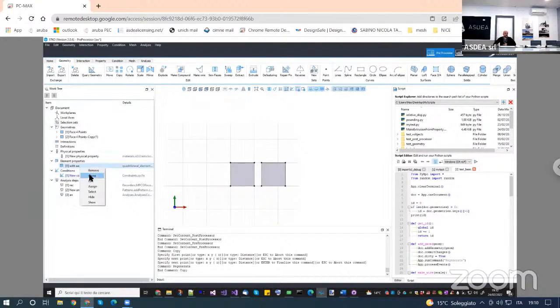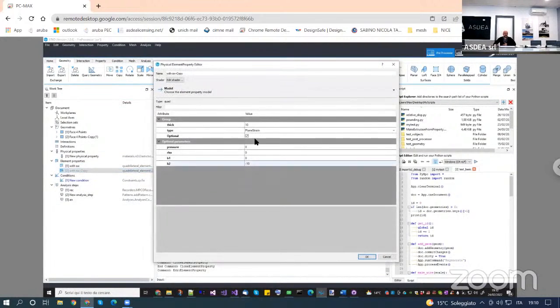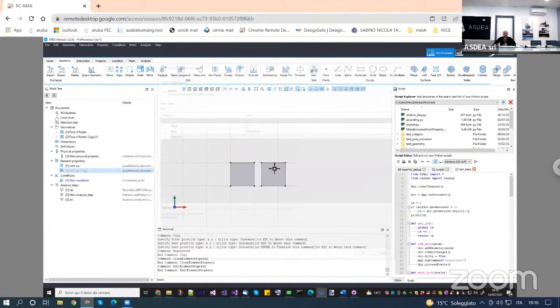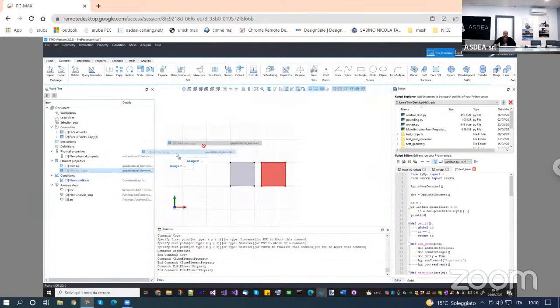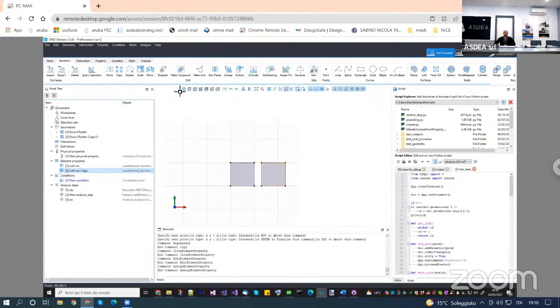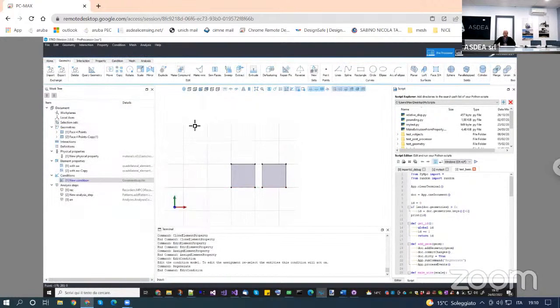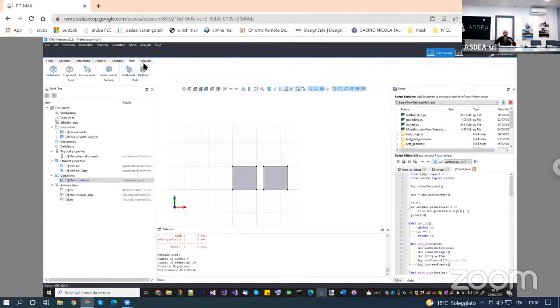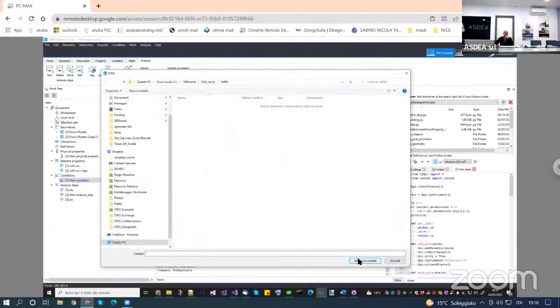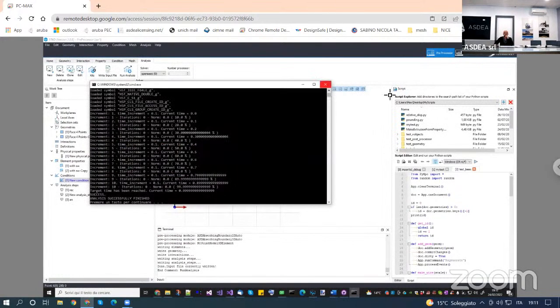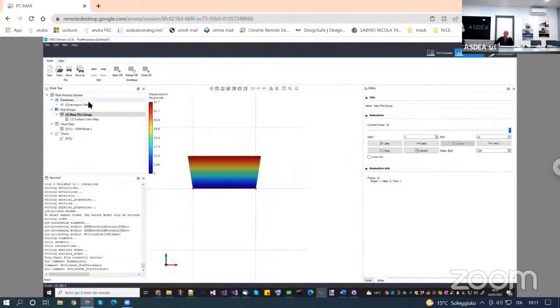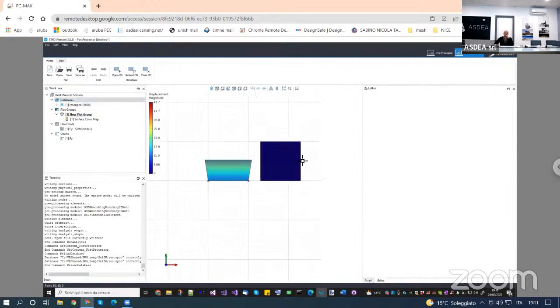different element. So let me clone this element, edit, and I don't want to use any self-weight on the second geometry, okay? So the second geometry doesn't have any self-weight. Now, of course, let me see, the fixity condition should be also here, otherwise it will be singular. Okay, mesh, build mesh. If I do the analysis now, I will see that one moves and the other doesn't, of course. Reload. Okay, so this one is not moving because there is no load applied on it.